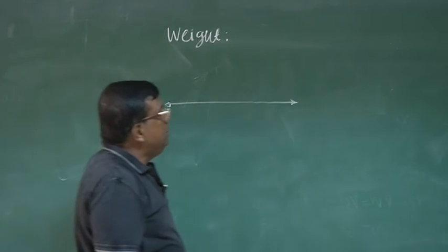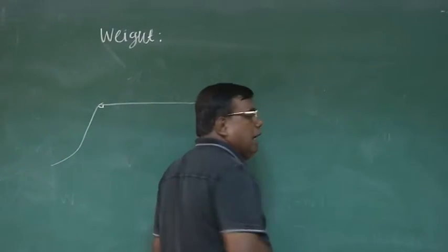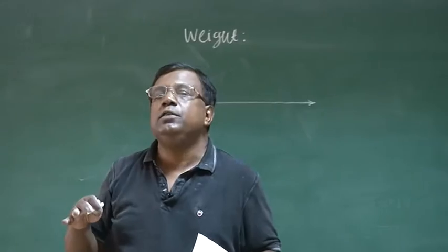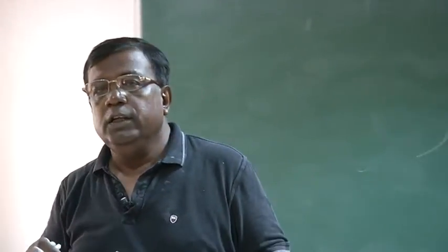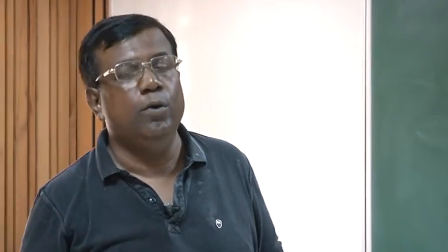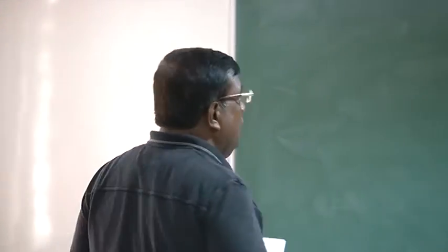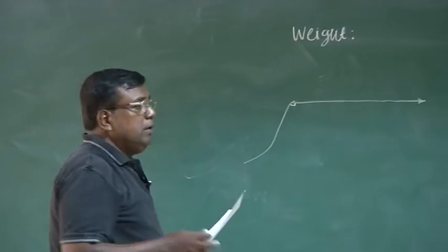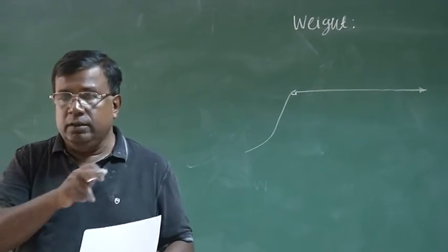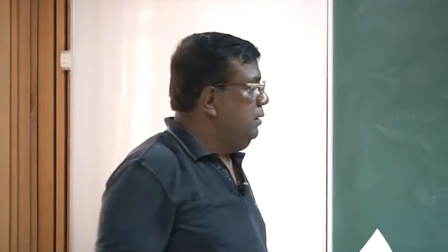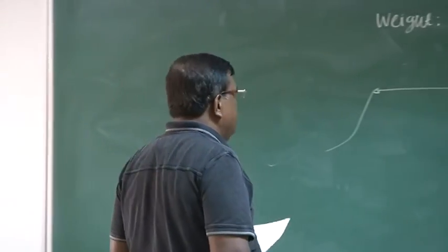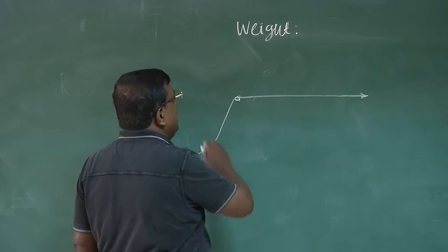Once the pilot says, yes, I am happy, I am at a cruise altitude of this many feet, you check with the altimeter, for your own learning, what is the pressure altitude there, you check the speed, you check the outside air temperature. That should be your routine thing. Whenever you are flying for an experiment, keep your eyes on the altimeter, airspeed indicator, outside air temperature, turn bank indicator. That will give a lot of insight into what this airplane is doing.